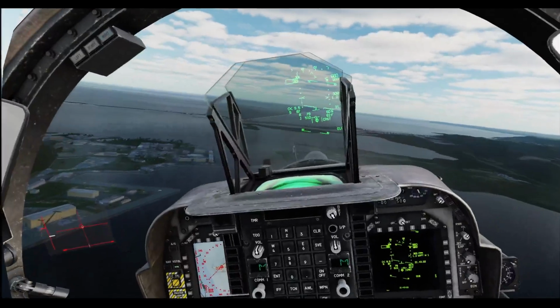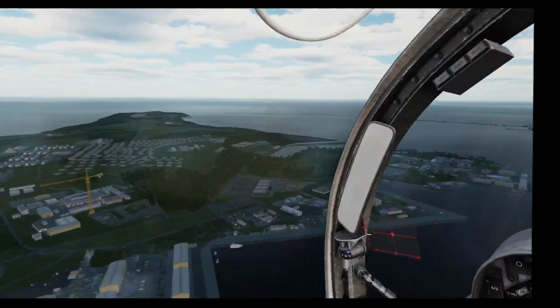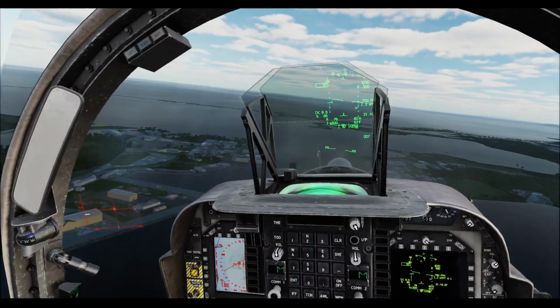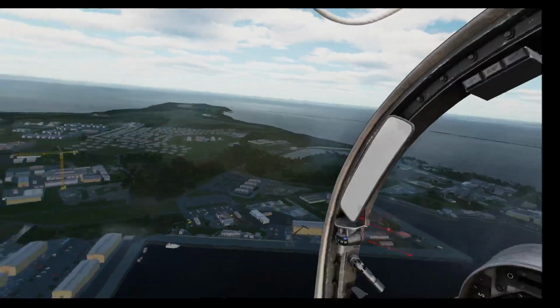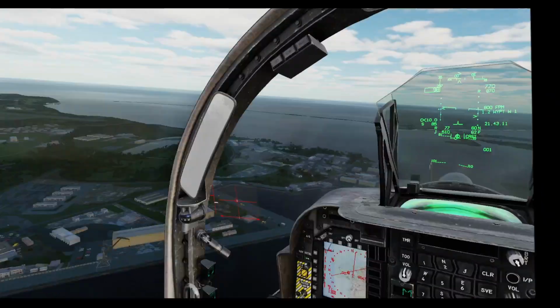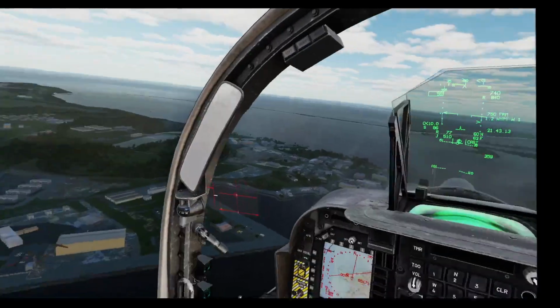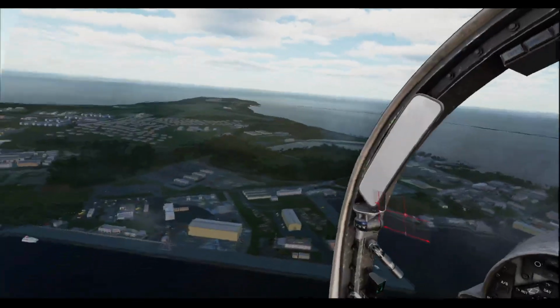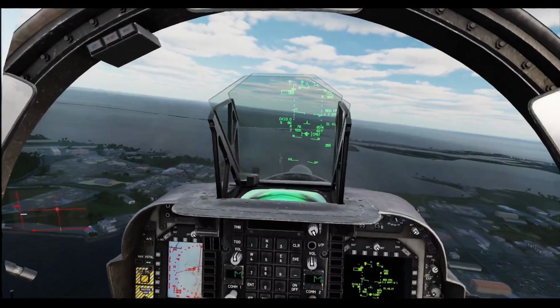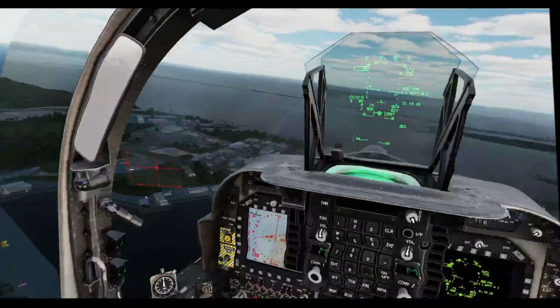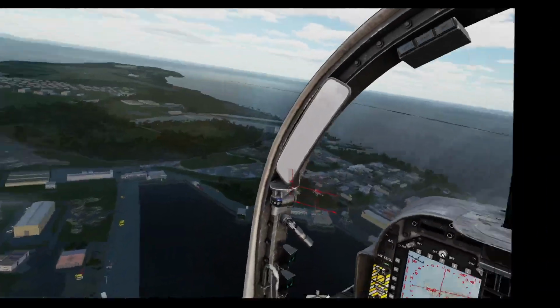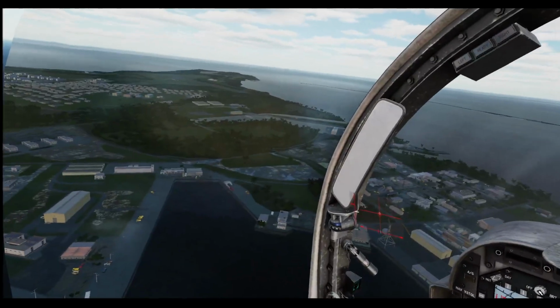Okay. Need to increase this rate of descent drastically. Airway is a little bit low. Might find that you square the turn off a little bit, that's absolutely fine. Always better to make the first half of the turn a little bit sharper than it needs to be so that you can be in the required position to make a good final turn.